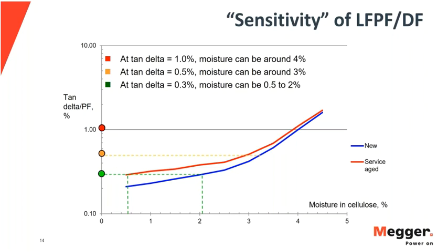It's not until the moisture in paper is probably at least 2.5% that the slopes marginally increase, and maybe 3.5% when the slopes notably increase, at which point it could be said that dissipation factor then has a heightened sensitivity to moisture when that slope really goes steep.